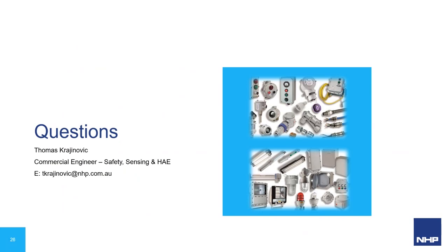Great, thanks, Tom. We have another question here from Derek. He asks, is the diesel tank room for generators in a hospital, can it be considered a hazardous area, zone 1 or zone 2? Would the light fittings or any other electrical apparatus used in it need any EX protection techniques? Okay, so yes, it is likely that that would be considered a hazardous area. So if you're not sure that it is one and there hasn't been a classification that's been done, you would need to go and seek someone to classify the area and make sure. But effectively, as I was saying through the presentation, there's the classification standards.